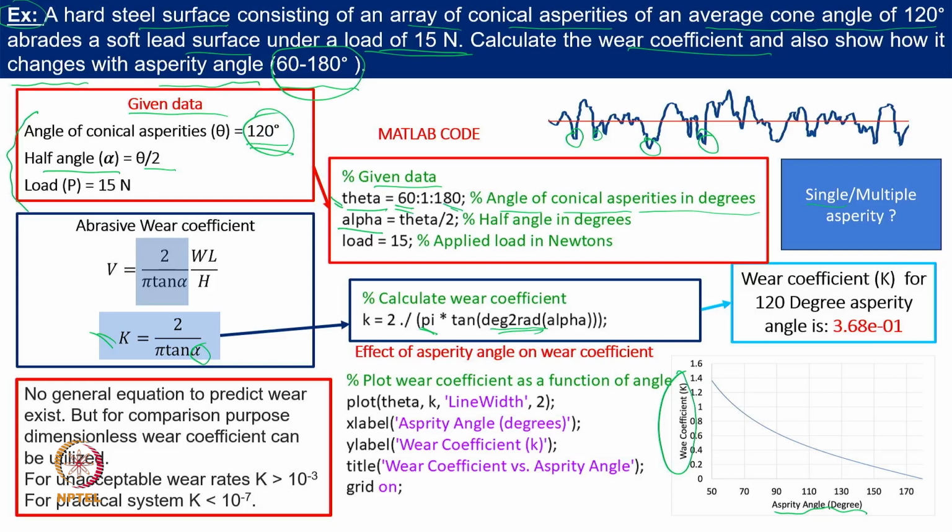So, that is important for us, and then maybe at around 60 degree it will turn out to be 1, it can be lesser, and again there is a probability, it is a number. We want a qualitative comparison, we are not seeing absolute comparison for us. So, this is what we are mentioning, and at 120 degree the absolute value we can find out, 0.368 is the value of this constant. And based on this we can say in reality we need to think about a multi-asperity model, not a single asperity model which has been given by this relation.